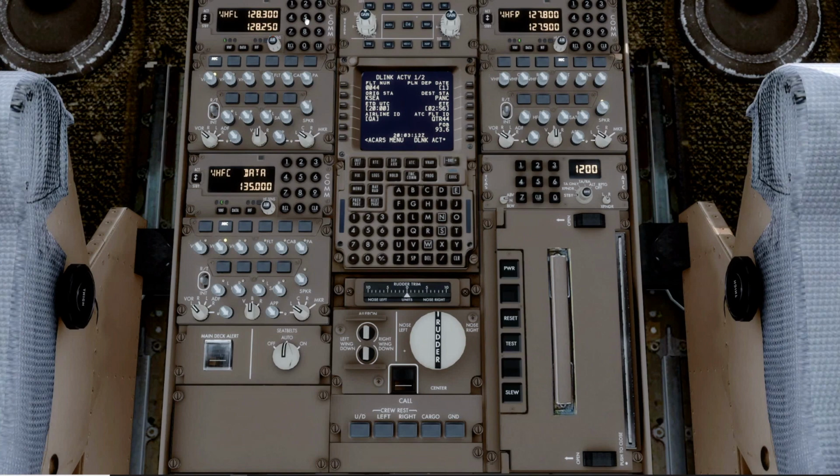So we'll make sure the radio's on, frequencies as desired. We can start to set them up. We're not going to do that. And then the audio control panel as desired. I've got the left VHF, I've got the speaker on if I needed it, and as desired. Check the center, it's on, data. Observers as desired. Seatbelt sign, I'll turn that on.